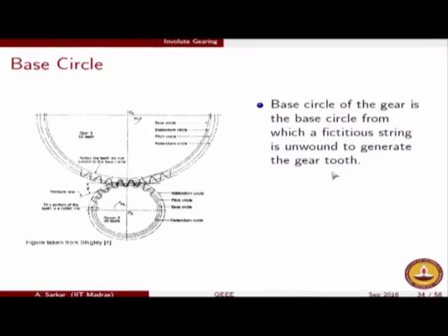In other words, from the cross belt pulley analogy, the base circle is exactly the radius of those two pulleys which were connected by the cross belt, and when the cross belt mechanism was moving, on each of these pulleys you are getting the involute tooth profile. So remember, the cross belt pulley analogy essentially should convince you that you are replacing the cross belt drive with the gear, where the cross belt drive will have the pulley radii equal to the base circle radius.